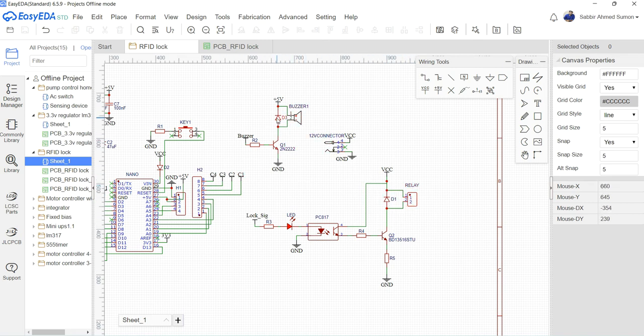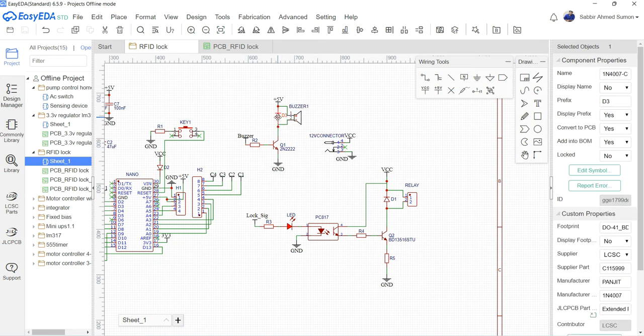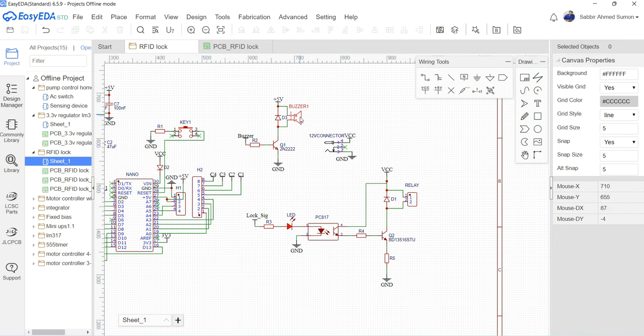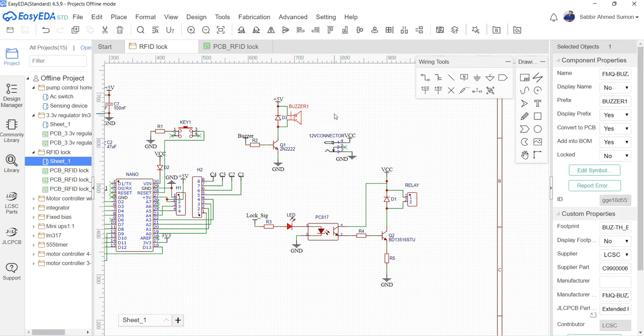There is also a flyback diode across the buzzer, because the buzzer also acts somewhat like a relay, but there is less possibility of damaging the circuit with this buzzer, as it is very low. It draws 20 times less current than this relay.